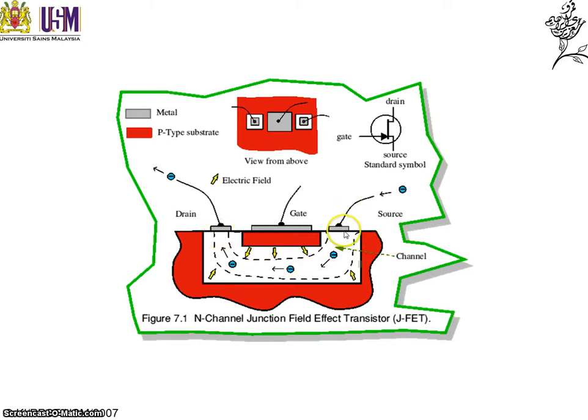So electrons flow from the source to the drain. These positive p regions, which is the red area here, are called the gates. If the channel were p-type, holes would flow from source to drain. It is common practice to connect the two gate regions electrically. Therefore, the gate voltage, VG, refers to the potential from each gate to the source.